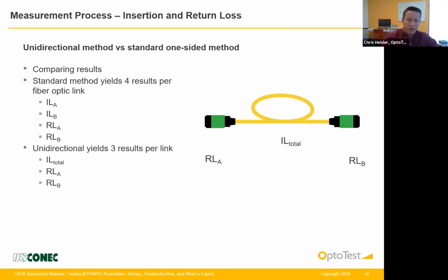Another one says, are the terms reference cable and launch cable used interchangeably? Yeah, they kind of are. In my presentation, I show equipment cable and launch cable. The purpose of the equipment cable is to protect the equipment. It's a large assembly that's difficult to connect and disconnect to the instrument, so you want to leave it attached the entire time.